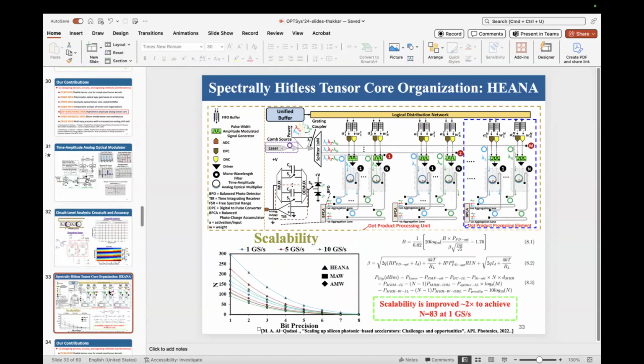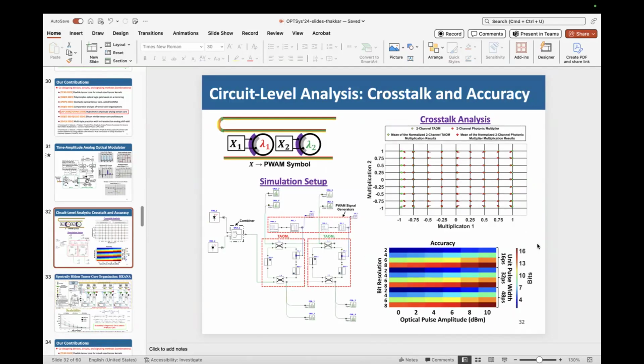I see. So for this architecture, you're using the output-stationary integration-based method, right? So here is an integrator. Typically the output dot product results will pass through some sample and hold, because for high-speed signals in analog computing, the output waveform will be a little ugly. So you find the middle point, sample it and hold, so you can have a square shape and do an integration, getting the area under the curve. But now you modulate the pulse width. So how does that work with this sample and hold integration?